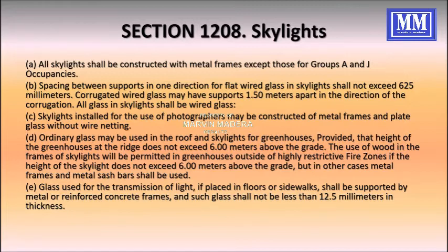Glass used in transmission of light, when placed in floors or sidewalks, shall be supported by metal or reinforced concrete frames, and such glass shall not be less than 12.5 millimeters in thickness.